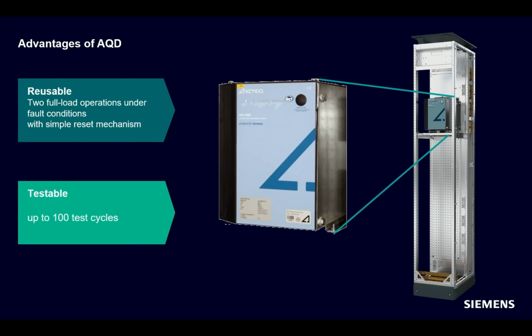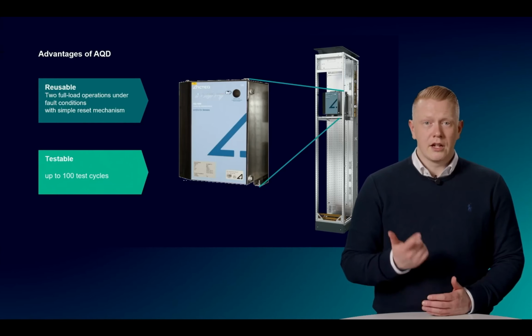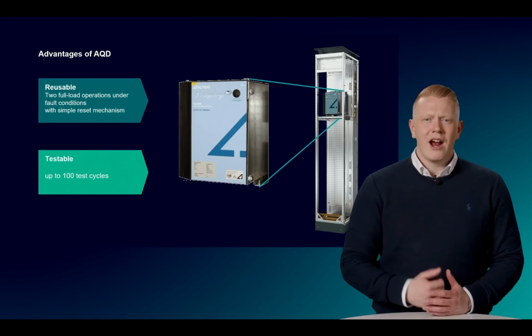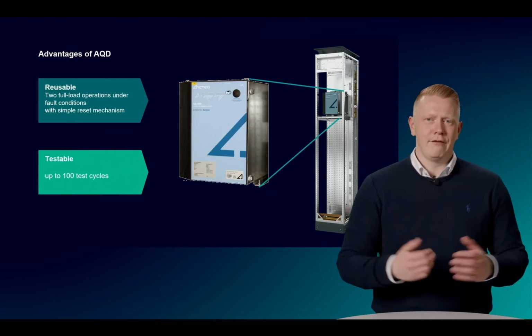And as the system can be used up to 690 volts, 100 kA, it can be installed in the majority of applications. This ensures comprehensive protection of the system-related processes, and the personnel. The three essential components of an arc fault, light, current rise, and pressure, are detected and evaluated. A shutdown takes place quickly and safely.